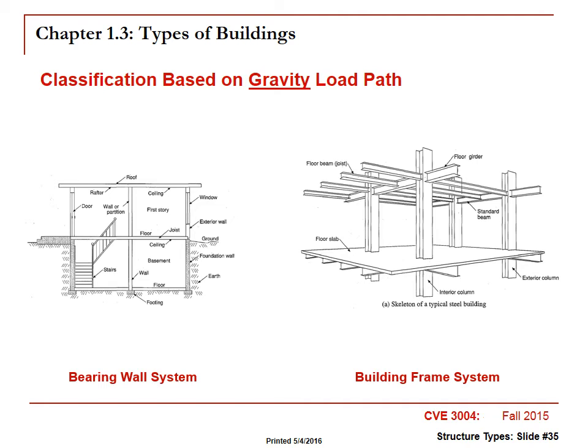So if you want to call it the first floor, it has a roof, and that might be a rafter or a roof beam or whatever it is. And those loads on the roof are being transferred to the outside walls, maybe to an inside wall. If it is to the inside wall, that's called a bearing wall. If it does bear gravity loads, there better be something underneath it that also is capable of taking those loads and transferring them on.